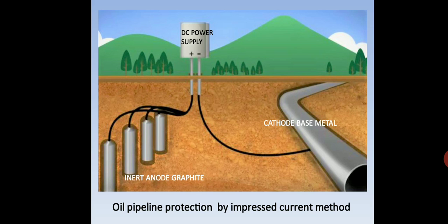In the current, there will be generation of a corrosion current. In this manner, the reduction reaction takes place and our corrosion product and all occurs. That's a different thing. So if by any means we can supply those electrons externally, there will not be any case of the anode undergoing oxidation, hence there will not be any corrosion.